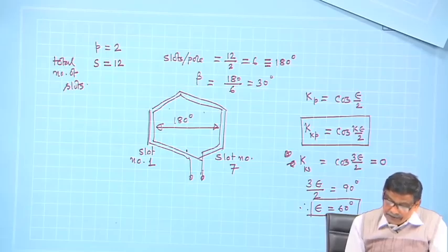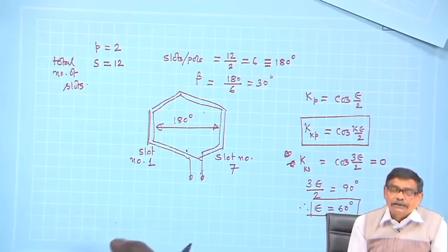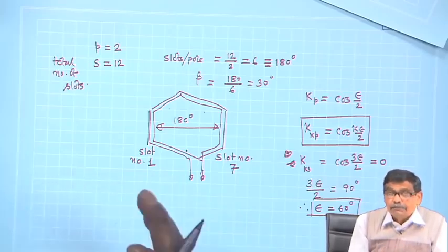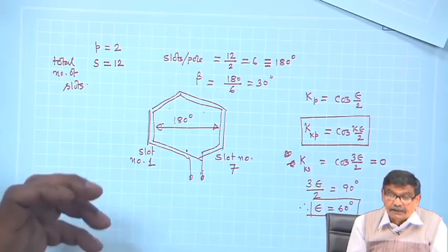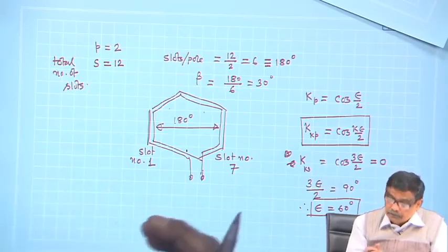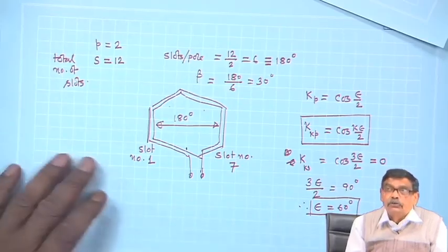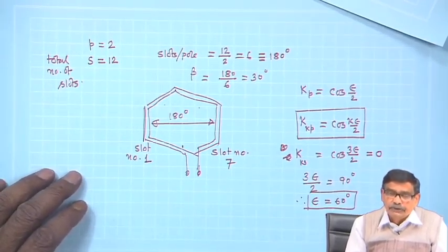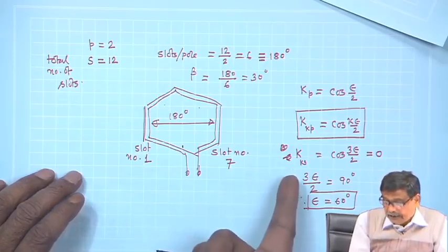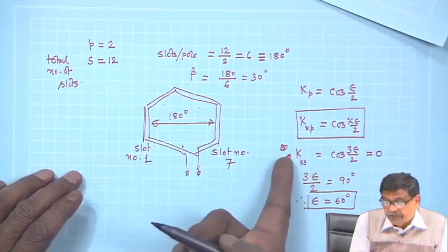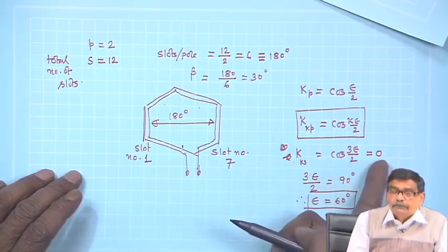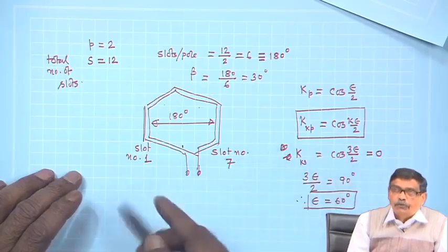Therefore, while making the winding, do not make a full pitched coil, because in this machine I find the third harmonic flux is very large, B is large suppose, and I want to see that no third harmonic voltage is induced. That can be done by making the appropriate pitch factor of that particular harmonic 0, then you are sure there will be no voltage.